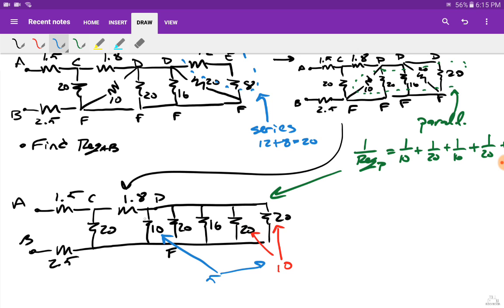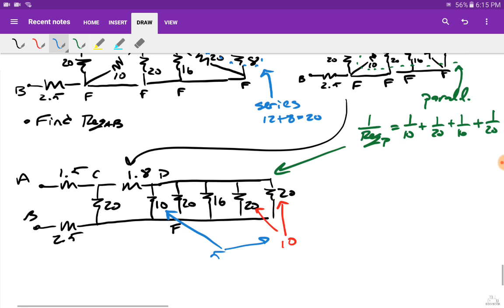Okay, so now I had 3 resistors, and they've broken down into 1 resistor. So I have 1 that is 5, the 20, and the 16. So I have 3 resistors left. All right. Now from here, and this is just because there are little combinations that I remember: anything in parallel with itself gives you half. 6 in parallel with 3 gives you 2. All right. 20 in parallel with 5 gives you 4.